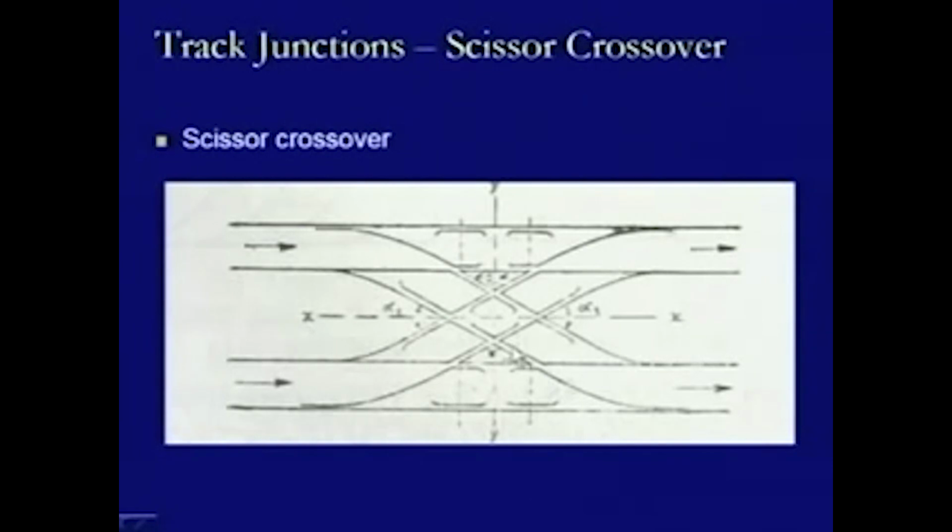So, we have a wing rail in this direction and in this direction, similarly a wing rail here and a wing rail here. This wing rail is extended so as to form a part of a diamond crossing, and so it comes here, goes this way, and becomes a wing rail again on the other side, for this acute angle crossing.